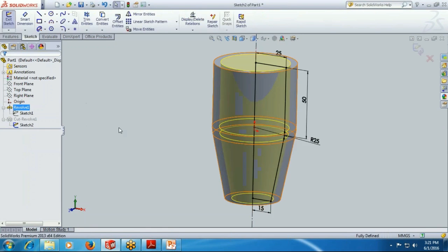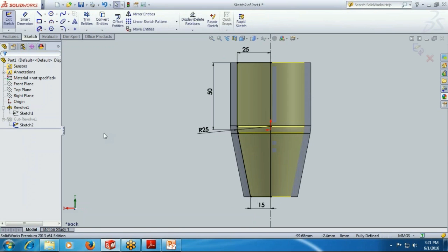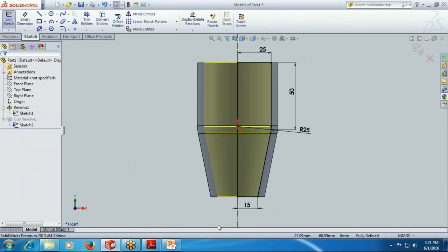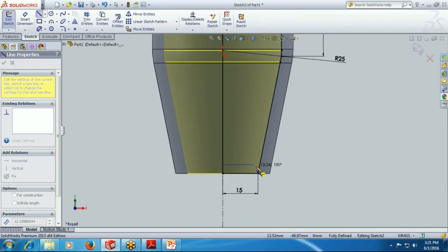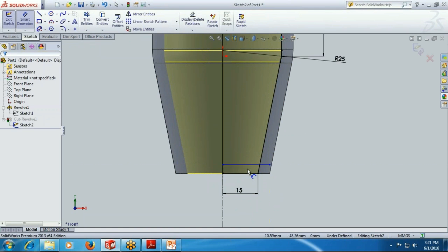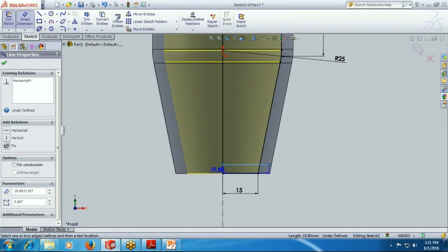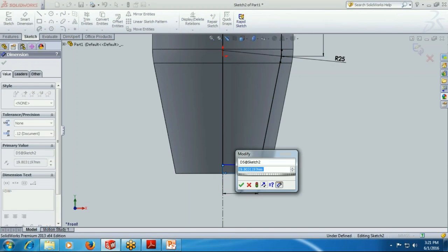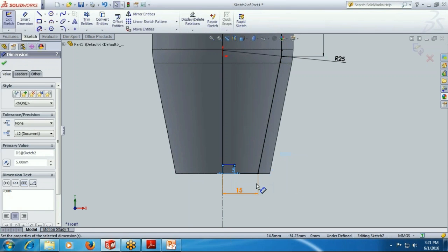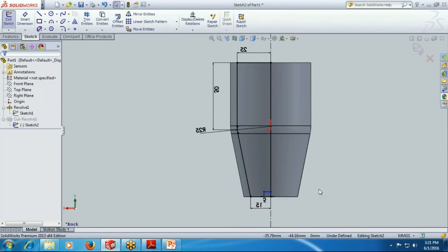Here is the option which is edit sketch, Ctrl+8, and now we'll see there this should also be offset to 5 millimeter. So I am just giving the line segment here, and now the size or the length should be 5 millimeter. Oh, that should not be done.